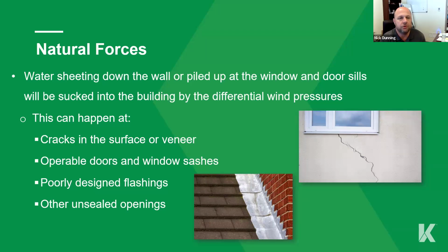But one of the most important things about water penetration is really the most obvious of cracks, open penetrations, things that have not really been maintained or just have naturally aged. And you want to go ahead and get them repaired. And usually you want to do that during your painting cycle. That's ideal. But these will happen in the middle of a painting cycle. It can happen after a storm, whatever it may be.